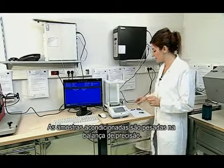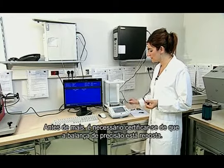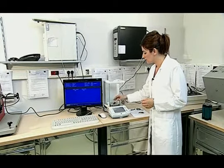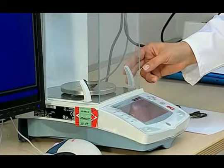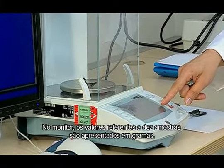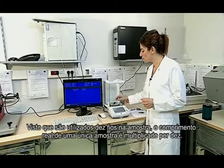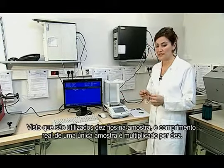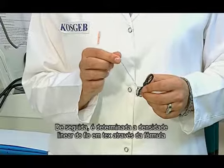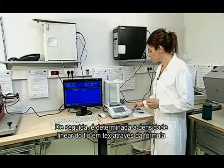We weigh our conditioned samples with the precise balance. Firstly, we ensure that the precise balance is at 0. On the screen, we read values for 10 samples in grams, and we record the values. Since we use 10 yarns in the sample, a single sample's actual length is multiplied by 10. Then we find the linear density of the yarn in TEX by using the formula.